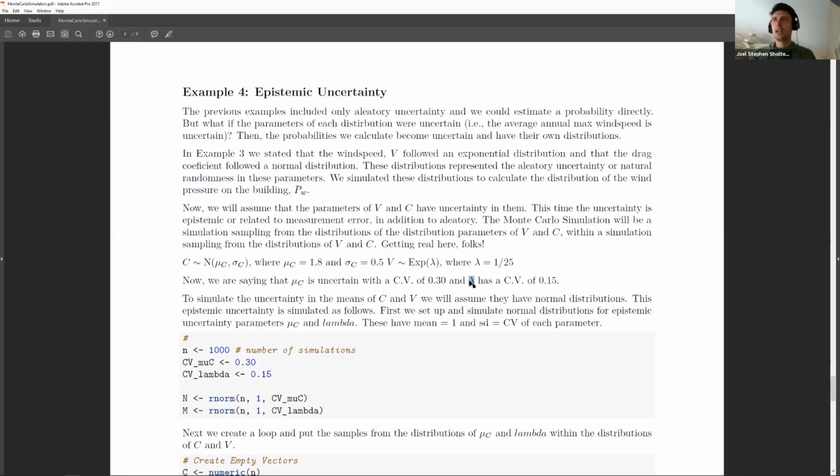It just means that when we're measuring the drag coefficient, it's a hard thing to measure. You have to use a wind tunnel, or go to a book and read a value, or do some calculation, and it's all based on lab data. And anytime we make a measurement, it's going to be inherently uncertain. So we're saying that these mean values we're using are uncertain, and we need to account for that uncertainty.